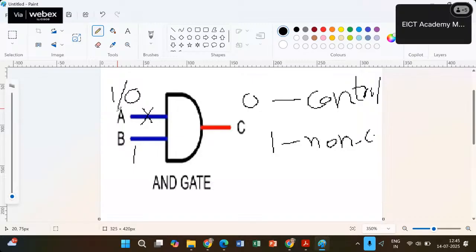We are going to represent it in this way. 1 means it is true and this is faulty. In order to find out what will be the output, if it is 1 and this is also 1, then the output I was getting is 1. So the fault-free output was 1. But because of the fault stuck at 0, I'm getting output 0 because of the fault available over here. So I will make 0 ANDed with 1.